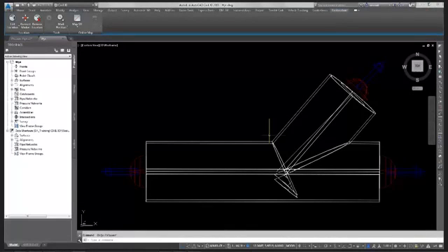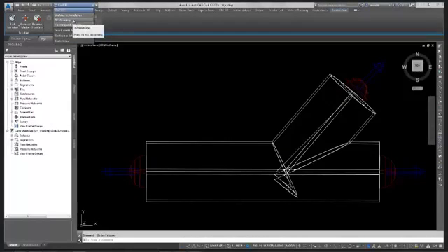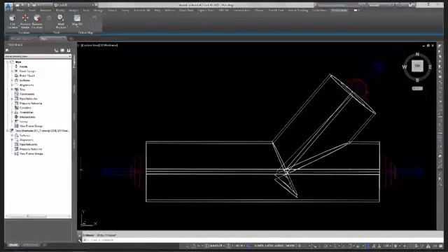What I did was I built my part using the workspace 3D modeling. I created a circle, I had an axis, I either extruded it, I followed the axis, I revolved it. However you build your 3D solid, it works. I built my part, and then I needed to add connection points. So I added 3 connection points into here. Connection point 1, 2, and then 3.